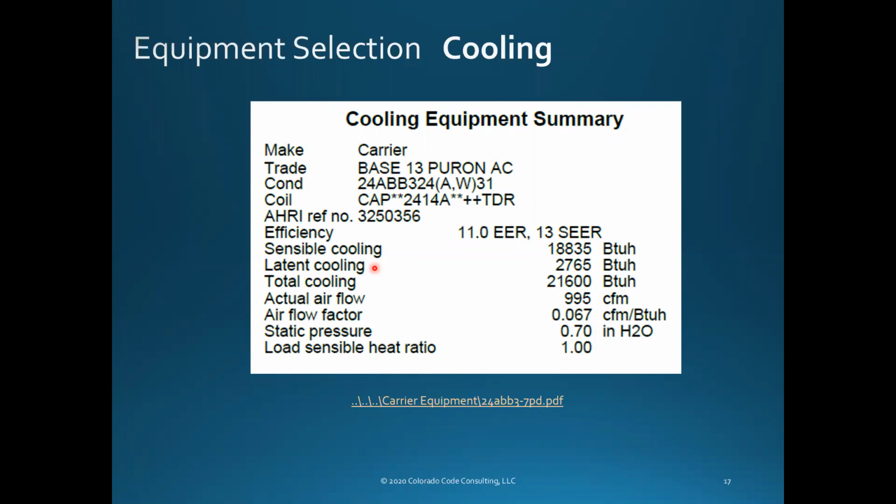And as the warm air goes through it, it cools it off. Well, the other thing that it's doing is that there's any vapor in the air, any water vapor, it's hitting that warm, moist air, is hitting that cold coil, and it's condensing. It's turning to water. Yes, that's the water you see coming out of your condensate drain.